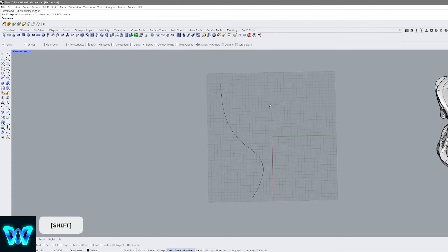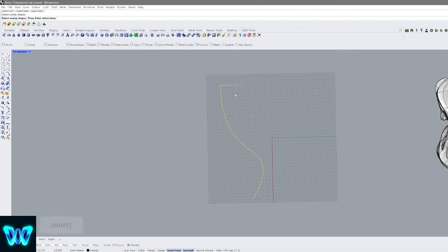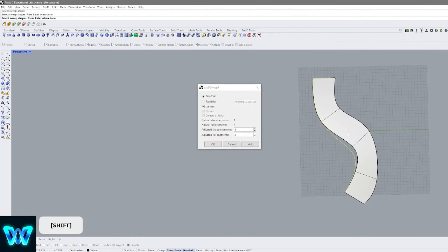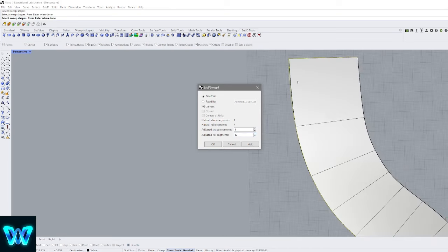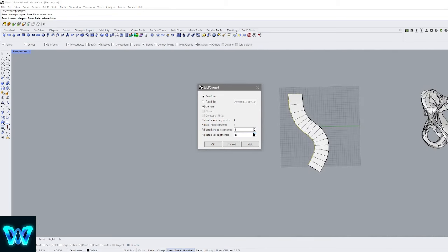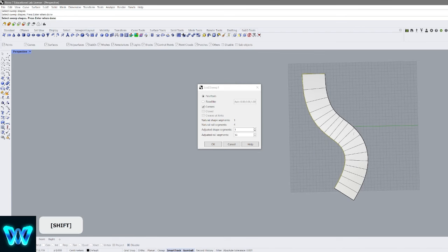So one of the things you want to do, for example, if I were to do the sweep, right, I want to maintain this very low count of polygons, because the moment I start to increase the polygons so it fits the curve perfectly, now I'm kind of stunting myself with the design, because now I have too many faces and then it gets complicated to work.